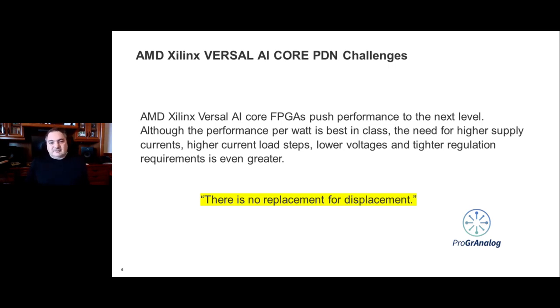You can't rely on simulations. I mean, they can help a lot, right? But at the end of the day, you can't release a product into the real world in any kind of volume environment without actually having tested the PDN. Now, you can potentially test it with the target device, but you can never go beyond what the target device can power.